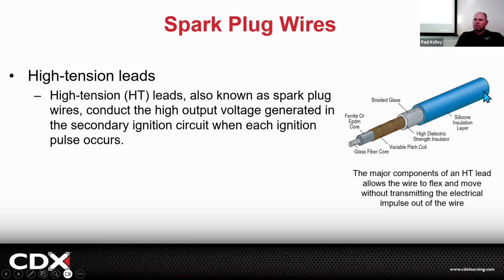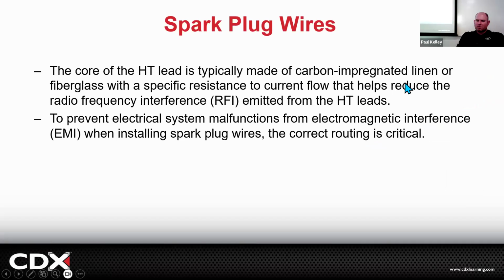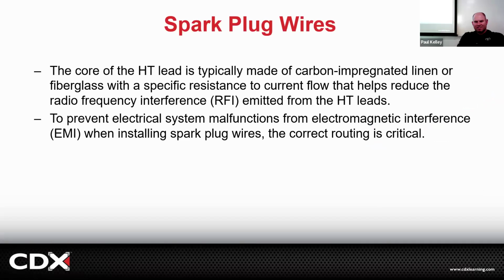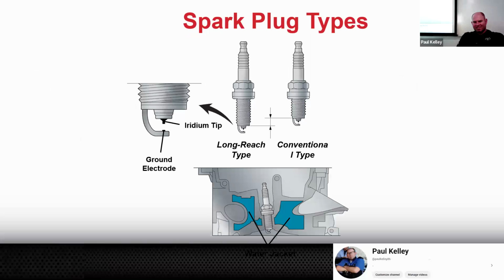If you've got some that you think might be bad, I'll show you a few tricks next time to test these wires out. Cool. So the high tension cables, it's not a real super big deal. It also sucks when this nice brand new spark plug cable lays on the exhaust, like the header. If you've got a new header, it melts it, so get another wire, because that'll make a direct short to ground and you'll have a misfire on that cylinder, that's for sure. Or just go ahead and grab it while it's running. You'll find out if it's good or not. But it won't kill you because it doesn't have a lot of amps.